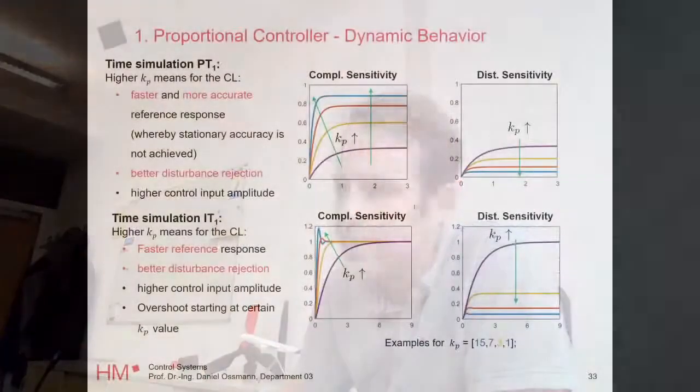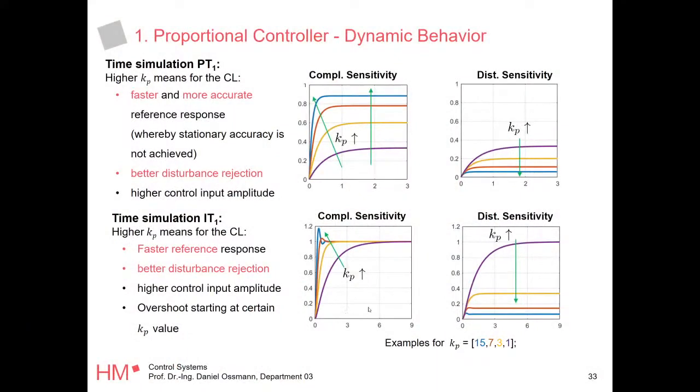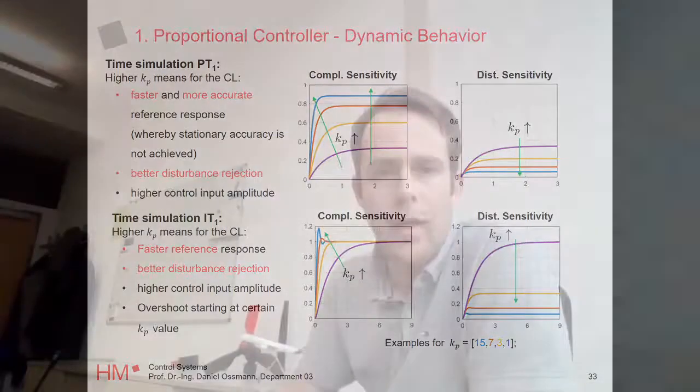Why is this guy oscillating? It's an integrating system with a first order lag. So we have two poles. What happens in a closed loop, and you should be aware of this, is that it is a PD2 system. It's a proportional system of second order, sorry, because we have two poles. Our system has a pole at 0 and it has a pole at minus 10. If we put a proportional controller around it, it gets a PD2. We are stabilizing our integrating system.